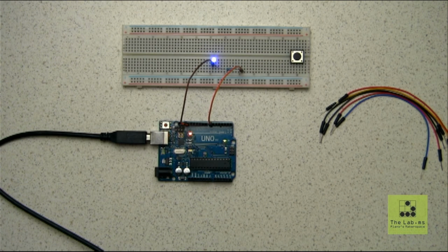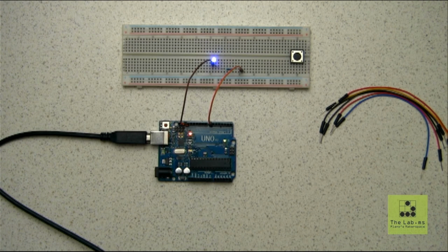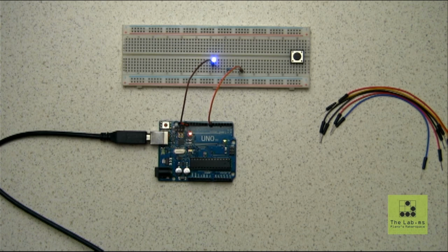And then let's see, how does it work to connect stage or level electric? Yeah, so if you have a Christmas light string, same thing. You could have those plugged into an AC power source, and then somewhere between the string and the power source, you need to put a switch with a controllable relay there, and then you would connect that relay to your Arduino, and then you would write some code that could detect things like time of day. It could be a light sensor. So when the ambient light values get below a certain amount, you can switch that relay on, and that'll turn the Christmas lights on.